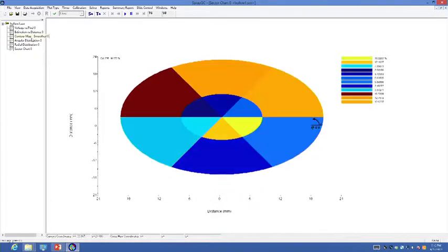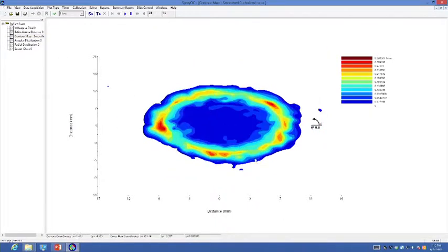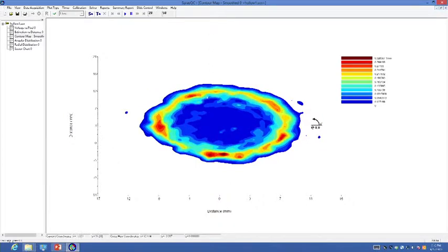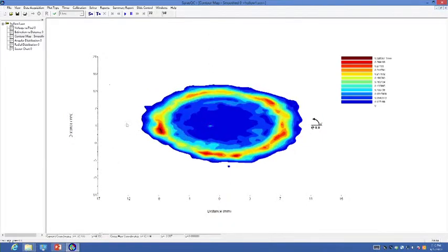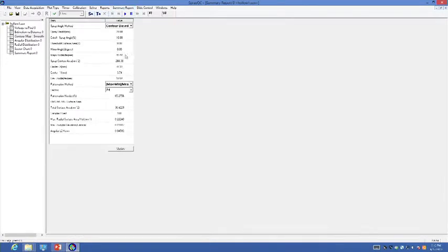You can see that if you go back to the contour plot, there is a small rotation that comes because this is a swirl stabilized atomizer. In addition, you can see the summary report. For example, you can see how the spray angle keeps changing with time. It varies from about 48 degrees to 50 degrees.